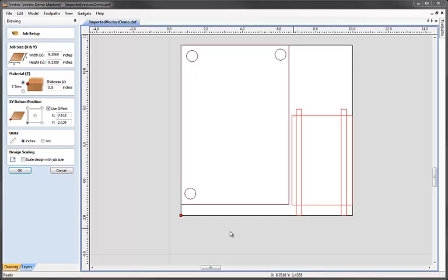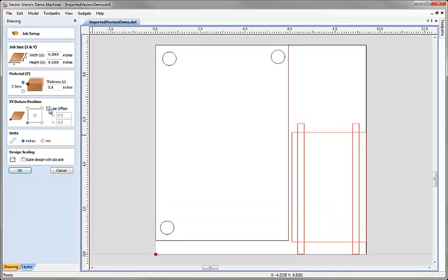Now we don't have to keep the geometry in this location. In fact, we can turn that offset off, but be aware that this will now move the position of that geometry from the world positions that it was originally in when saved in the file, and it bumps it back down to 0, 0 here. So now we have an origin based on 0, 0. We don't have to accept the job size. We can change the job size here to anything we like.